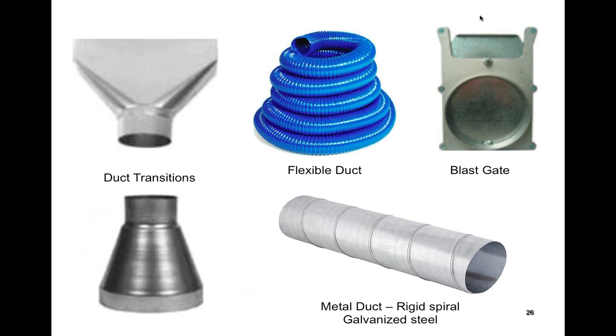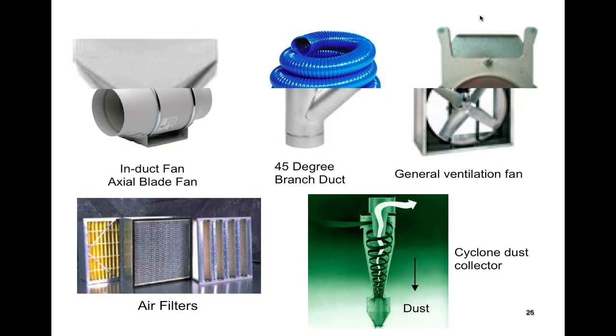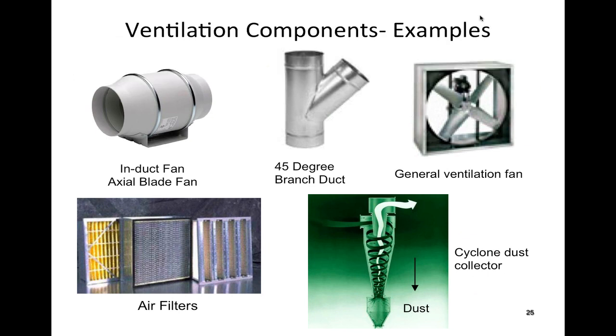Cyclone dust collector. What that basically does is as you pull air through it, the air goes into and out of a device that spins the air very quickly. So if the particles have some mass, they're going to be thrown to the outside, collect down at the bottom.